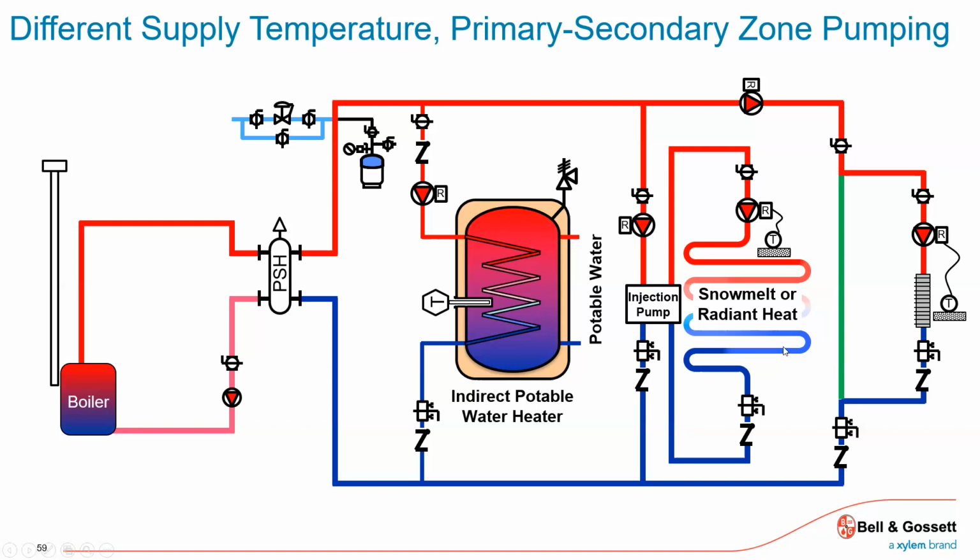And sometimes when they don't understand that, they'll set up a scenario where I got heat everywhere. I got heat in my zones, or my domestic hot water is 180 degrees. The Aquastat's not even calling. I pulled the Aquastat out because they piped it just like you described. And then all of a sudden, that pump is in series. So it has to go.